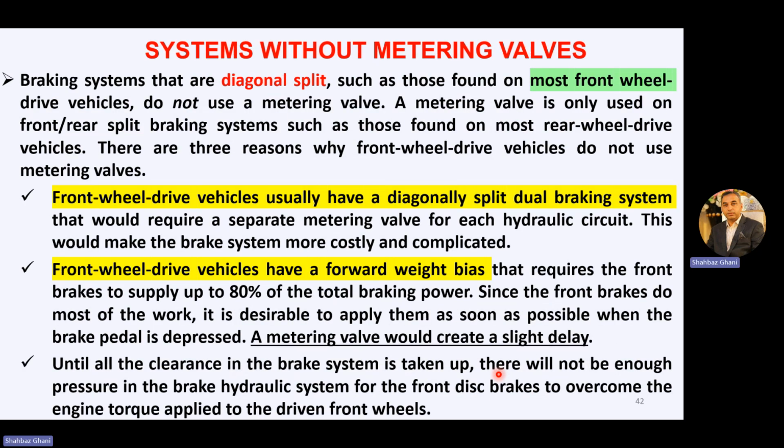Now, systems without metering valves. Braking systems that are diagonally split, such as those found on most front-wheel drive vehicles, do not use a metering valve. Diagonally split means front right and rear left, front left and rear right. So they do not use metering valves.